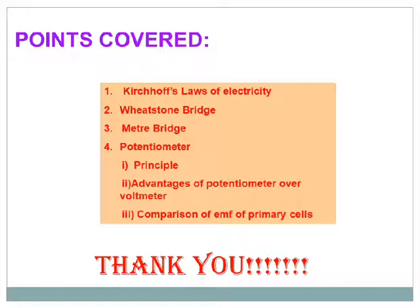In the potentiometer, we have seen the principle, which is V is proportional to L when the current flowing through the circuit is constant and the resistivity is constant. Even the resistance R should be constant, only then V is proportional to L. Second, the advantages of the potentiometer over the voltmeter, which we have discussed, and the comparison of EMF of cells. The individual cell method we have also discussed in this part. So all of these points are covered in this slide.